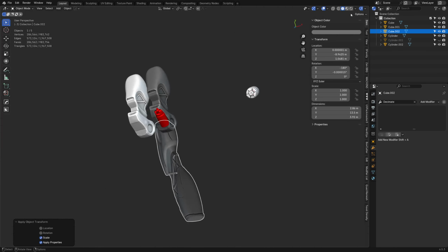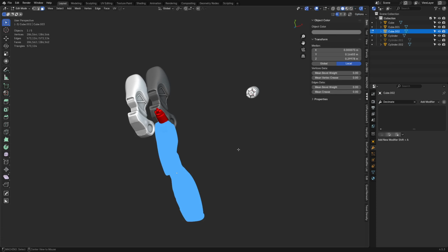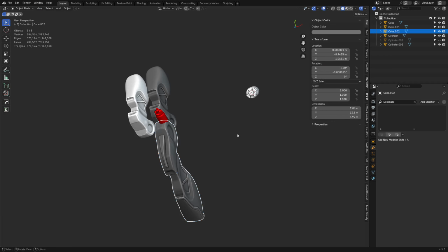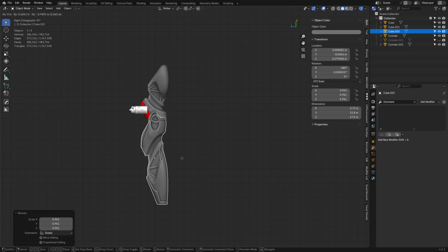It's going to invert your normals. If you don't see that, you need backface culling on. All right. Then go into edit mode, Alt N, flip your normal. That's a good piece now. And so we can use these in combination with each other.